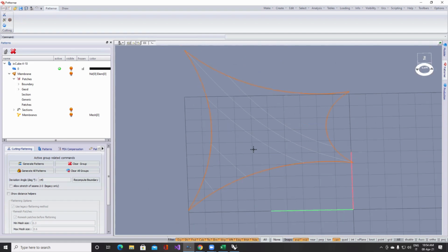We are going to slice the surface over these curves. The part of the surface between two consecutive curves and the boundary edges, we call a patch. It's a piece of surface, and the patches will be flattened on the ground into patterns. Okay, so this is the process. It's quite simple. We generate cutting curves, the boundary of the cutting curves become three-dimensional patches, and each patch is developed, smashed on the ground into a pattern. We have any freedom to define whatever we want.